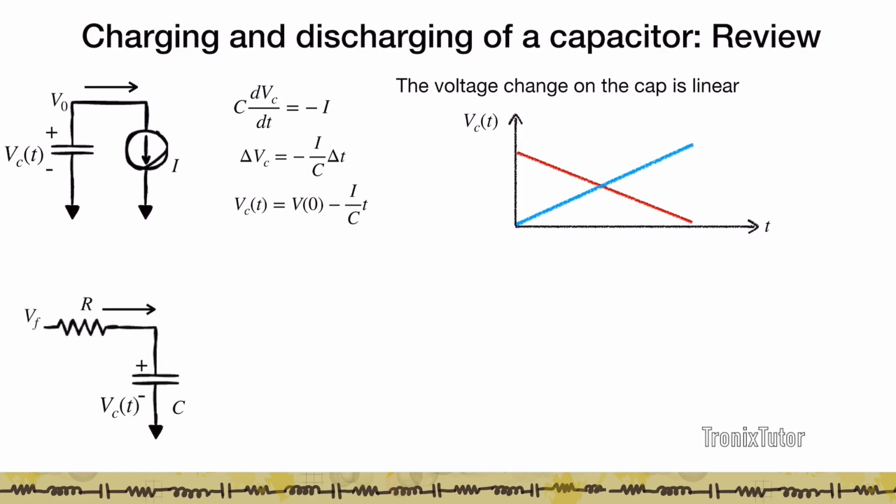On the other hand, if I think of charging up a capacitor through a resistor and a voltage source, this is an RC network, a first order circuit. So I can write RC dVc/dt + Vc = the charge up voltage, in which case during charge up I'm going to have a profile across the capacitor which is an exponential rise.